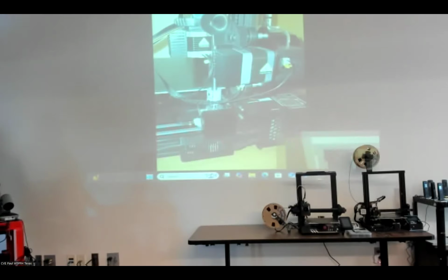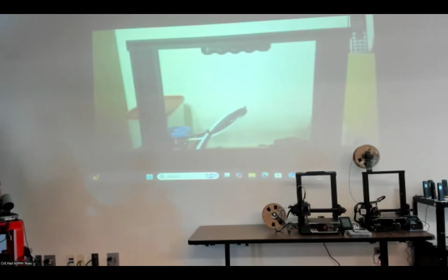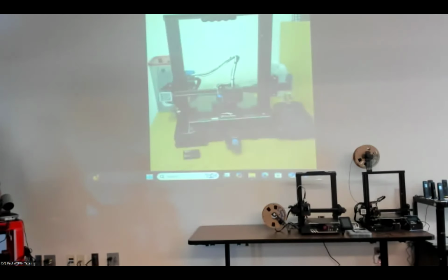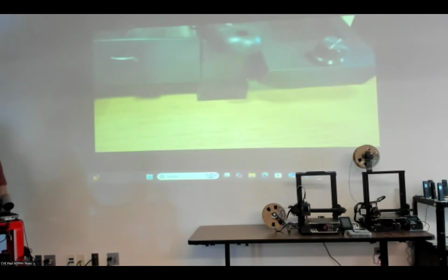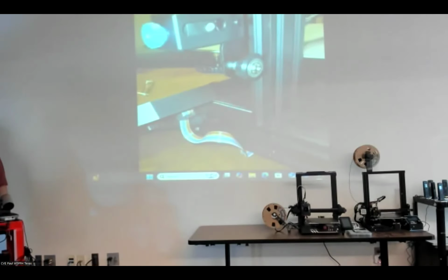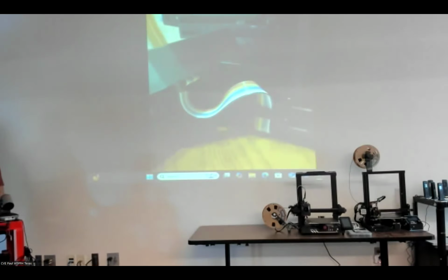And I say waterlogged, we're not talking about the spool weighing any heavier or the filament looking any different. But it gets just enough moisture that the layers don't lay right and adhere right. Especially with a spool that's been set out for a while, the top layers are going to be more exposed to the moisture than the layers under them.